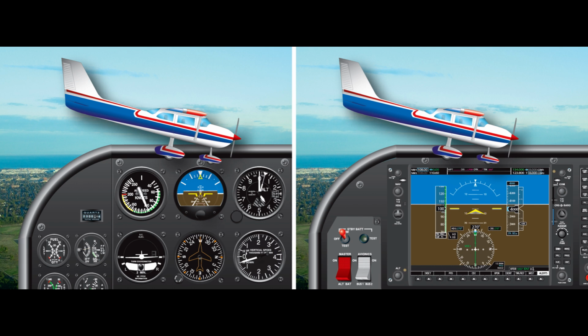3. Emergency descent. Some airplanes have a specific procedure for rapidly losing altitude. The AFM/POH specifies the procedure. In general, emergency descent procedures are high-drag, high-airspeed procedures requiring a specific airplane configuration, such as power to idle, propellers forward, landing gear extended, and flaps retracted, and a specific emergency descent airspeed. Emergency descent maneuvers often include turns. Glides.